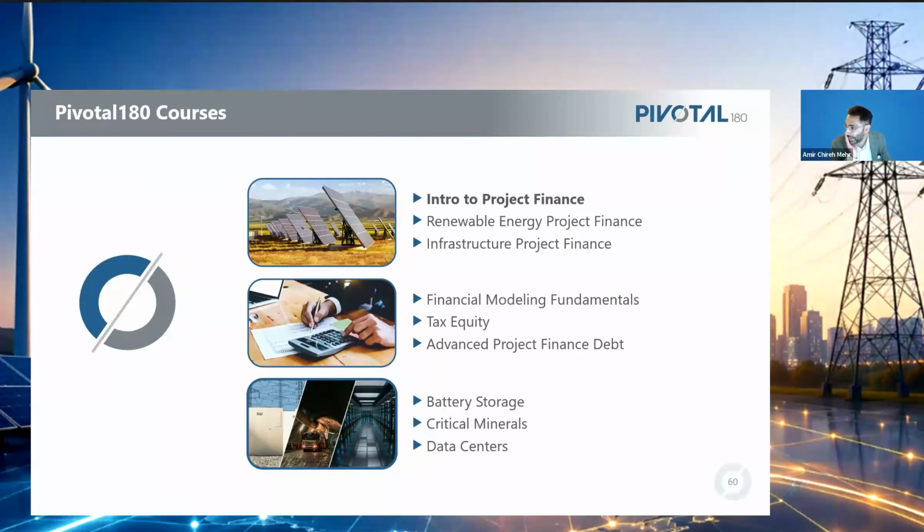So there's a question about the real-time market versus the day-ahead market. We'll try to get into this in the next session, but without going too much into the details, think of the day-ahead market as the marketplace where suppliers of power and the RTO, the Regional Transmission Organization, make their best guess at what next day's power requirements are going to be. They enter into a day-ahead agreement where I'm going to require you to deliver X amount of power at a price of Y. That covers about 95% of the load.